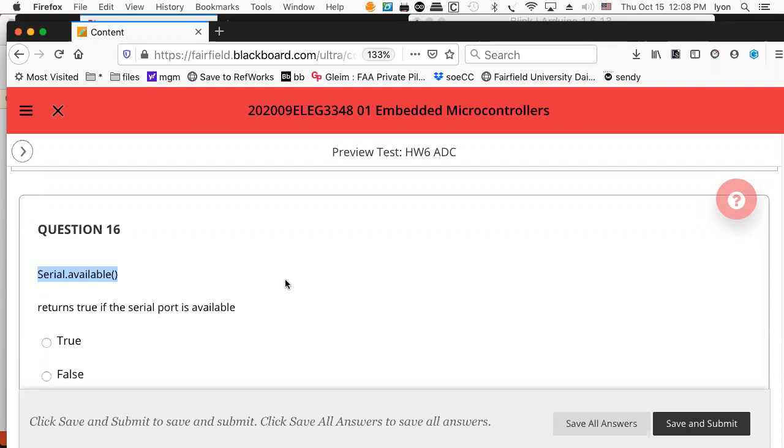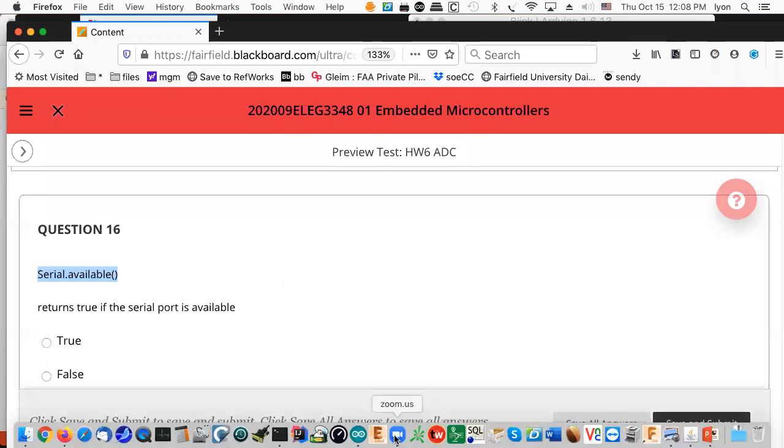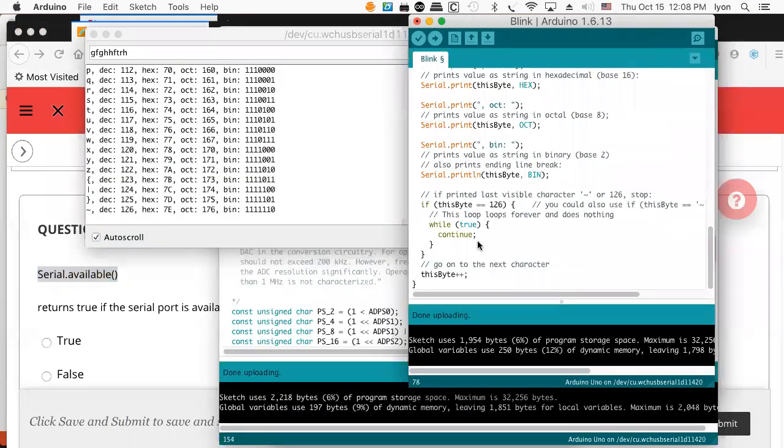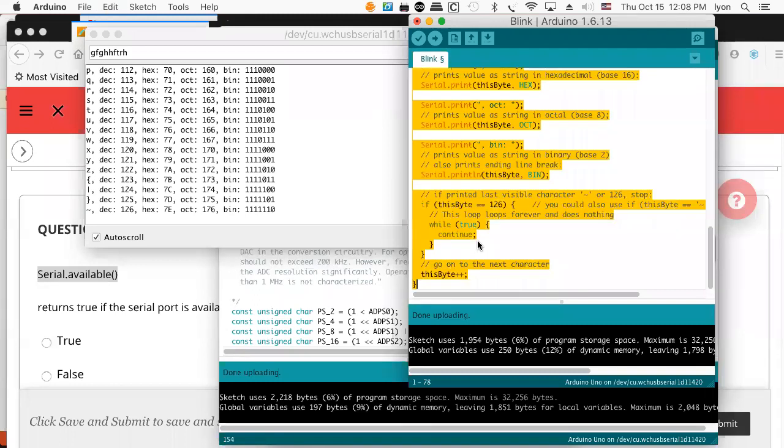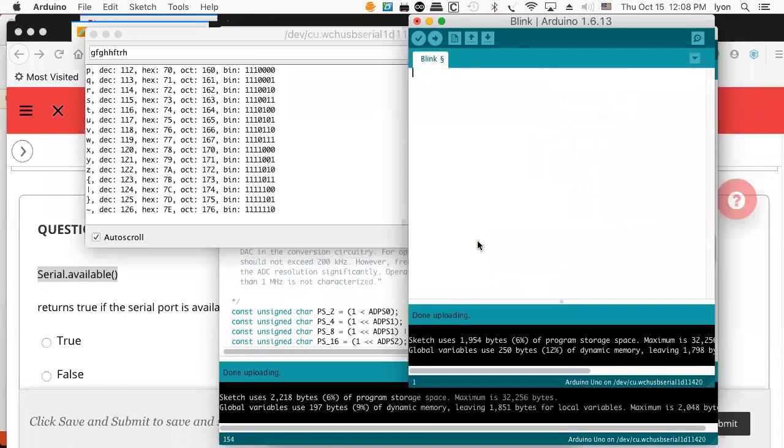So let's find out. Okay, we'll just do the loop. Let's give it a go. Why not? Certainly, we are able to do these things. So we'll put in a setup, and we'll do a serial dot begin at 9600. And then what we'll do is we'll do a loop. And we'll have to say if the serial is available, it's greater than 0, means it's available.